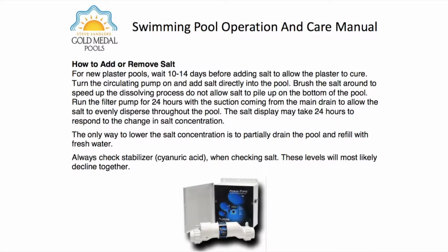The salt display may take up to 24 hours to respond to the change in salt concentration. The only way to lower the salt concentration is to partially drain the pool and refill with fresh water. Always check stabilizer or cyanuric acid when checking salt. These levels will most likely decline together.